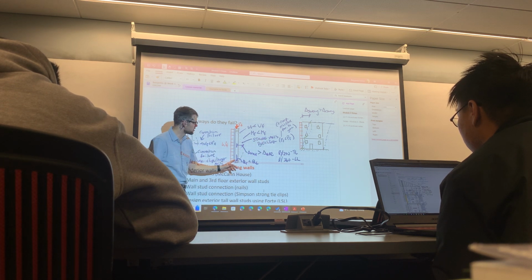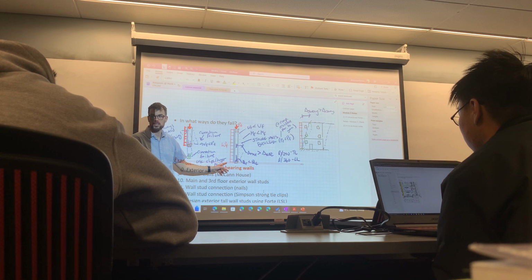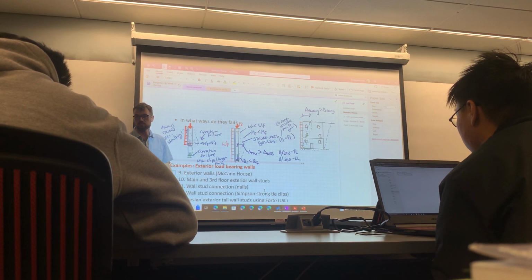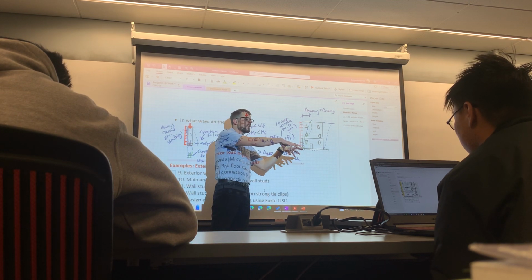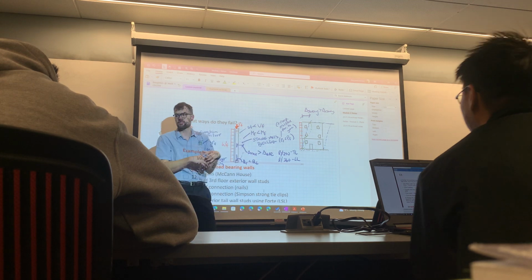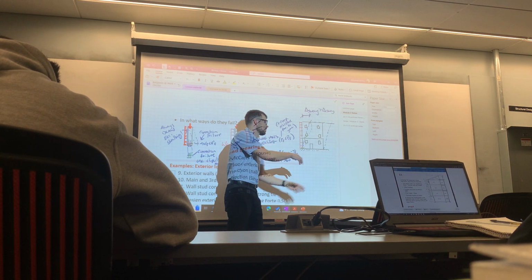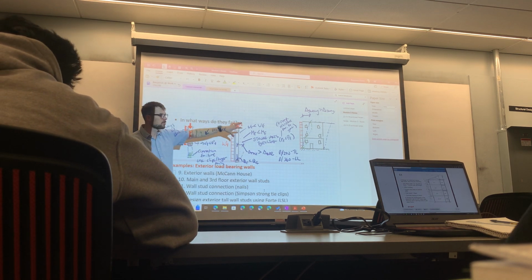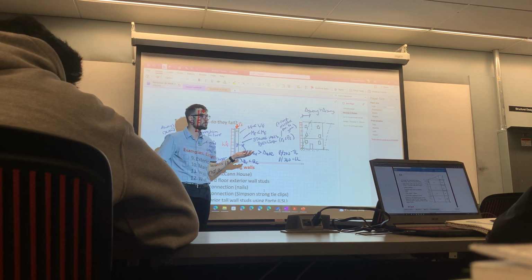So you do have to provide some temporary restraint on this side, or you have to pull back enough on this side to make sure that it doesn't fall over. People don't usually push the wall over, but what happens is you stand them and your bracing's insufficient and a big wind gust starts, and then all those walls pull down. And once one goes, even though the other ones have openings and let the wind through, it just pulls it down like a big train. So, has anybody experienced that before?